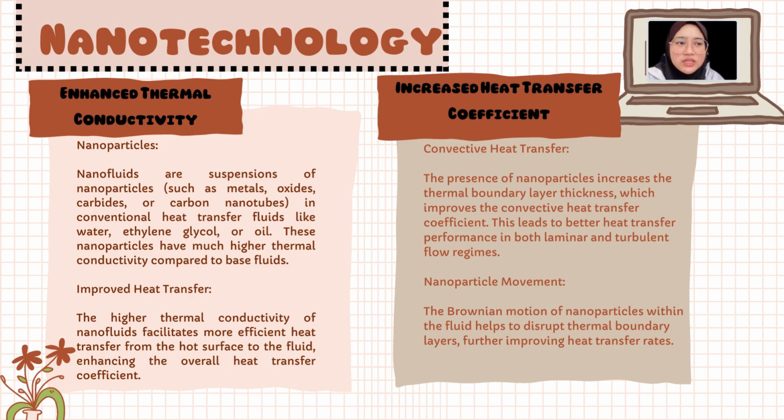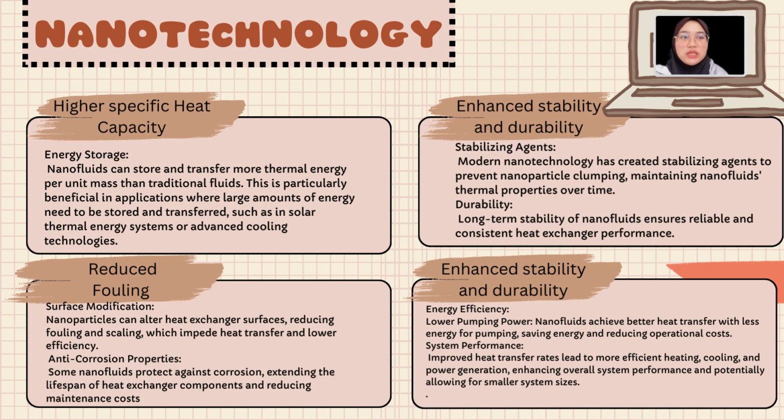The presence of nanoparticles increases the thermal boundary layer, improving the convective heat transfer coefficient and leading to better heat transfer performance in both laminar and turbulent flow regimes. The Brownian motion of nanoparticles within the fluid helps to disrupt the thermal boundary layers, further improving the heat transfer rates. The nanofluids can exhibit higher specific heat capacity compared to the base fluid, allowing them to store and transfer more thermal energy per unit mass. This is particularly beneficial in applications that require significant energy storage and transfer.